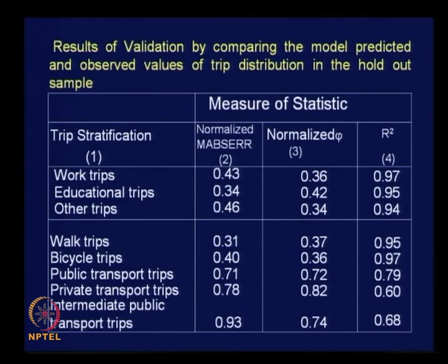So, this is how the gravity models were applied for a particular case, and the models that we discussed so far are gravity models based on Newton's law of gravitation. The input data to these models, if you can recollect carefully, are trip production and trip attraction values, Pi and Aj, right, and then the data corresponding to travel distance or travel time. These are the inputs to get Tij value,